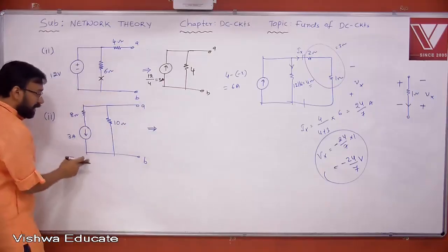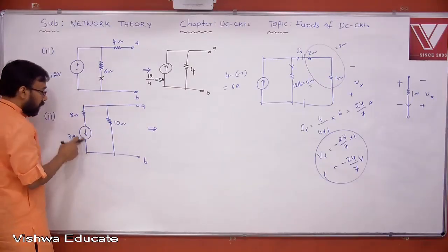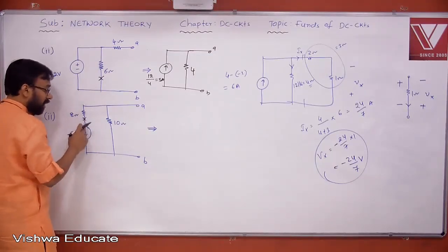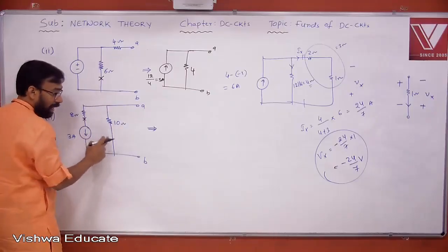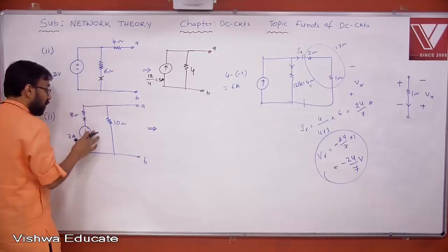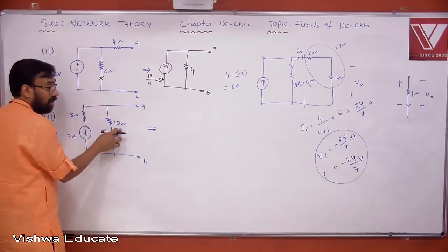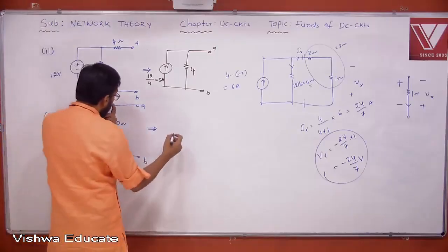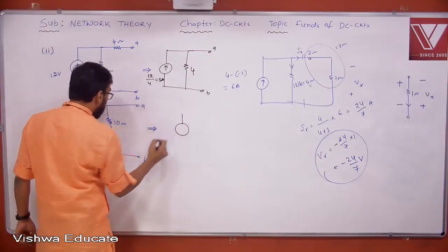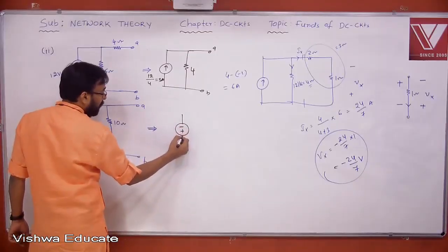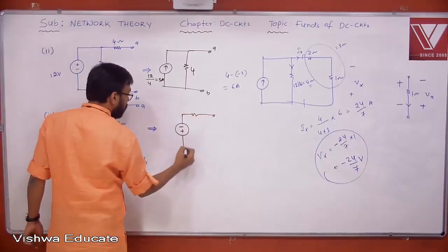Okay. Now coming to this. Any element in series with an ideal current source can be neglected or not? Neglected. If this is neglected, then how do these two elements look? Parallel combination. Now the current source with a parallel resistor can be transformed to what? The voltage source with a series resistor. But now, since the current direction is downward, you must take minus and plus.